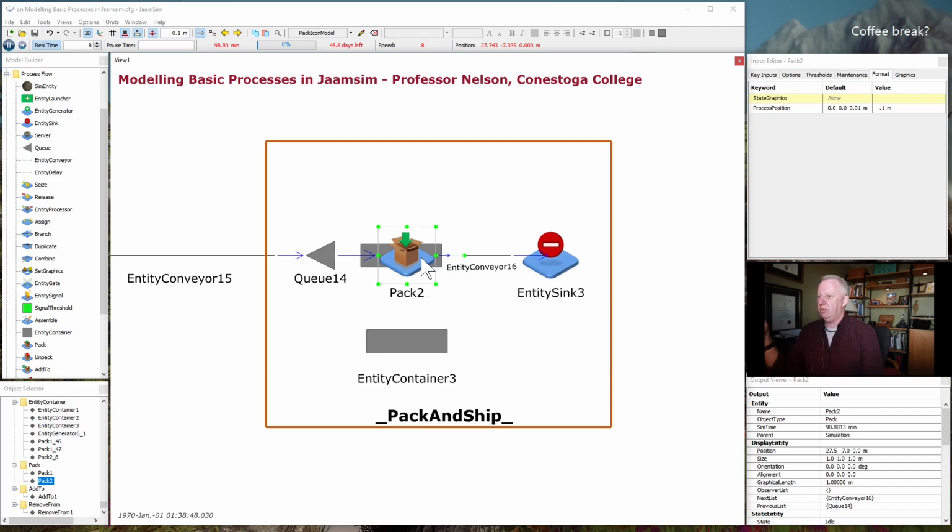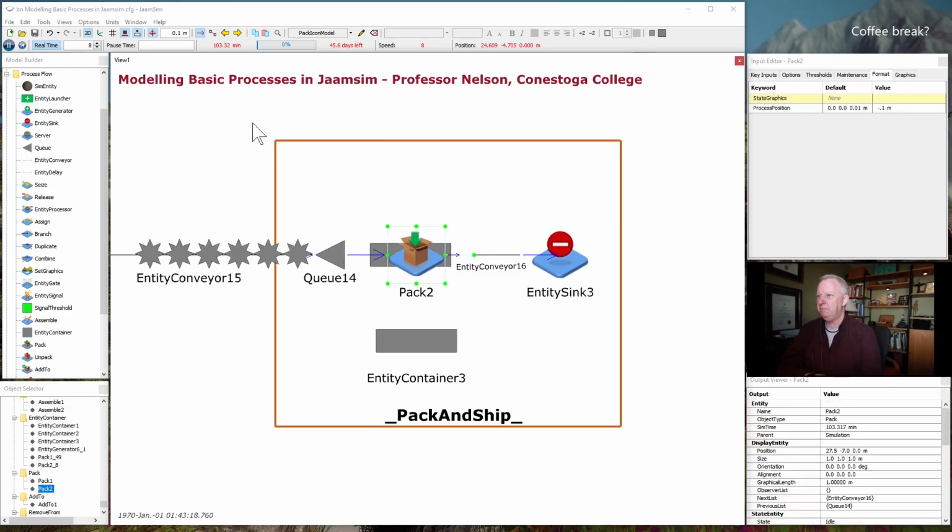I've also done one thing. You can see I've got the container in behind. Normally in a model, the container will show up on top of the processing element, and I think it looks a little bit better to tuck it in behind here. So on this first axis, I put a small negative number, and in 3 dimensions, this probably looks a bit weird, but if I put a small negative number here, then it shows up in behind like this, and it helps again the visualization of your model.